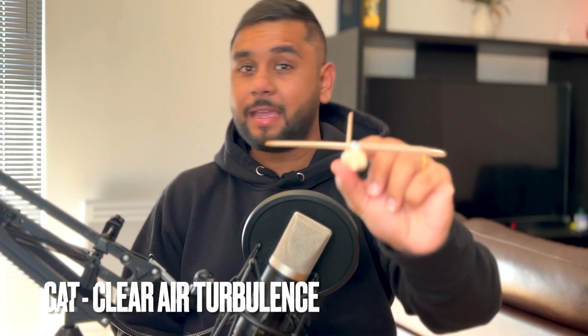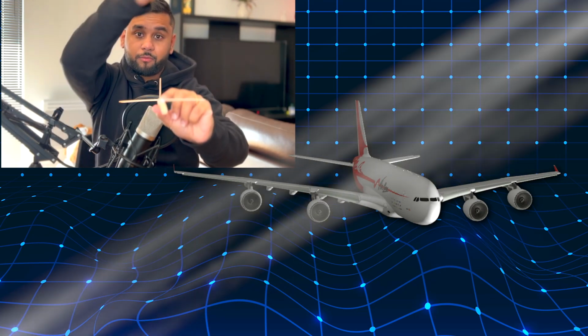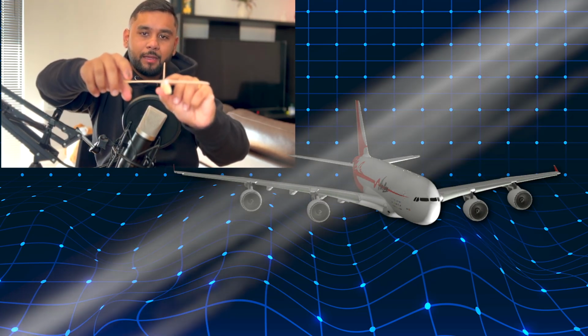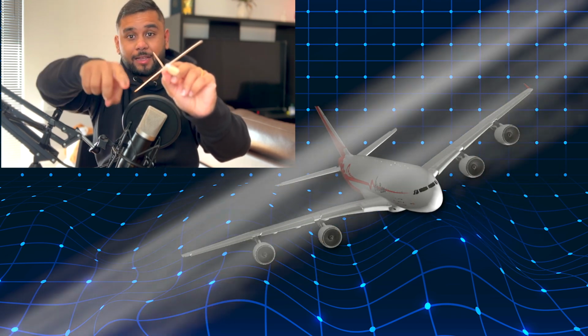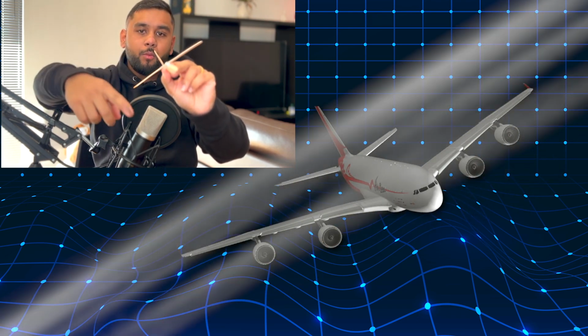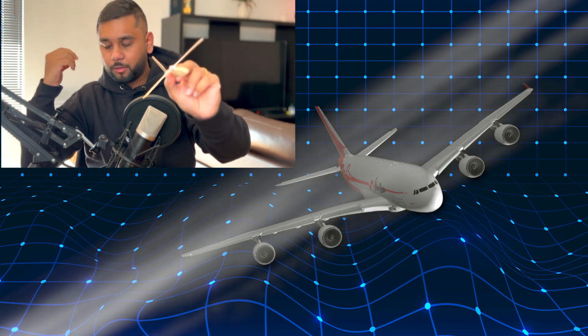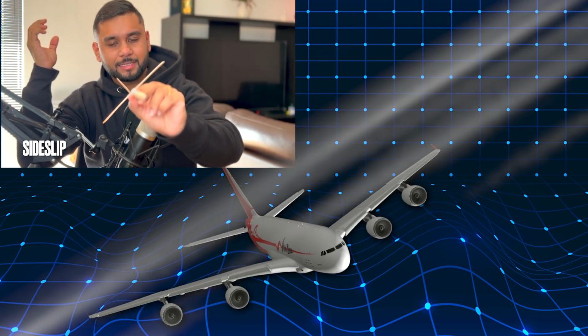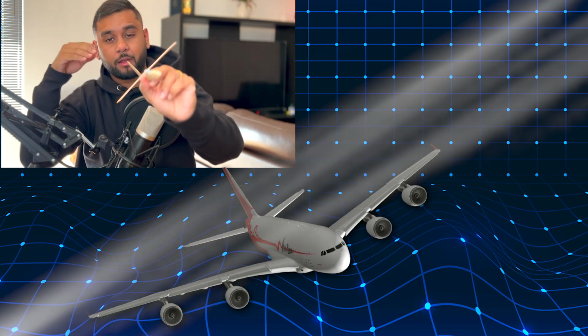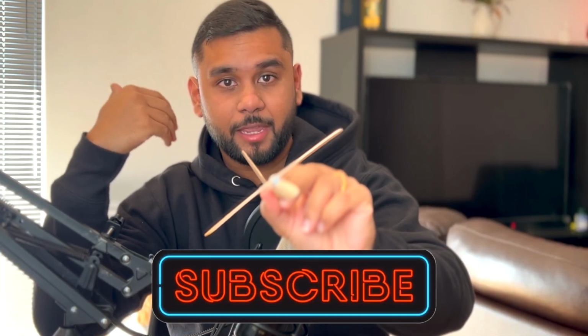Let's just say a mechanical turbulence occurs. One part of mechanical turbulence is CAT turbulence, or clear air turbulence. So a CAT turbulence might come as shear forces, like shear wind forces. So let's just say now there's a shear wind force coming from this end and it hits this wing and drops this wing. Now it has rolled down. So when a wing drops, or when the aircraft is in a roll, it can cause something called a side slip. A side slip is movement of the aircraft sideways relative to the oncoming air.